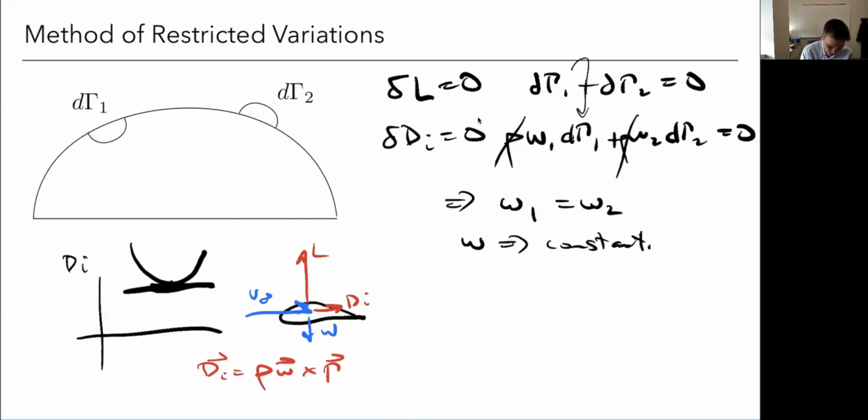And if I did it on the other side, so let me just erase this real quick. Here's the other half of my wing over here. Right, we get the exact same thing, only just opposite. V would be like this, and I get a force this way. So they'd be exactly the same. So these two sideways components would cancel out, but I have a component that's facing forward. In other words, it's a component of thrust. And this is one explanation we sometimes hear about winglets, that the purpose of a winglet is that it generates this induced thrust, right? So that's going to reduce your induced drag.